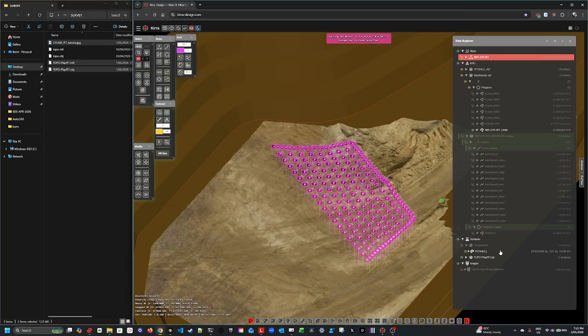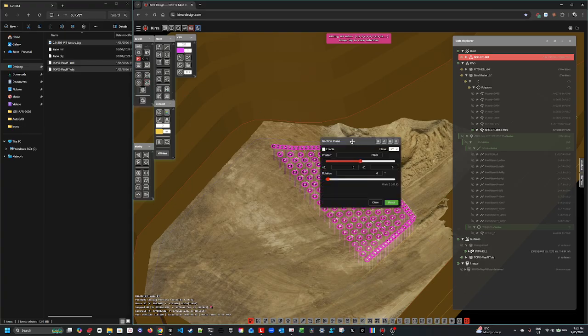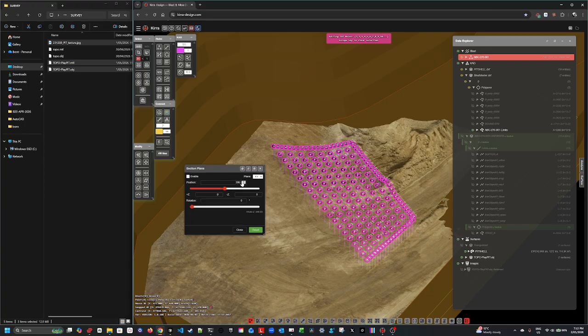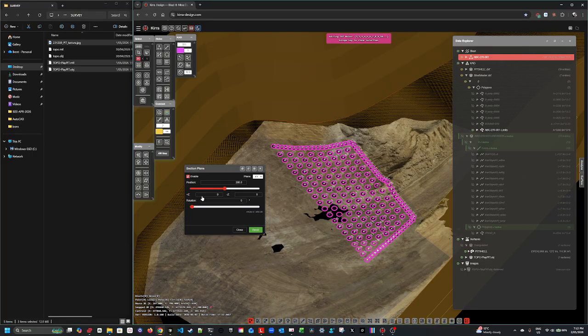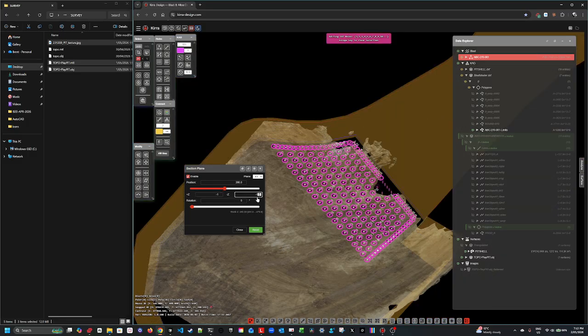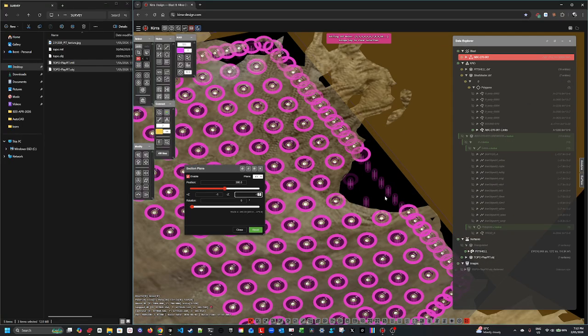Let's have a look at that. I think we can use this section plane. Okay, and so we can set this to 280. That's the top of the hole, and enable it, and it's going to chop our 280, and we'll just dial this back here, 1 there, -1 there, so it's going to give us, oh, so this is the area that's a little high in our bump.